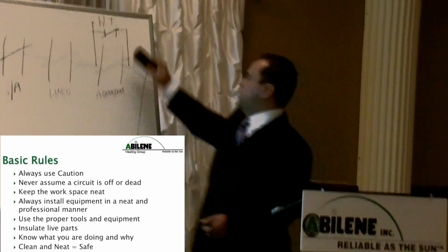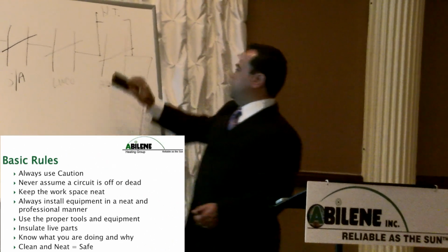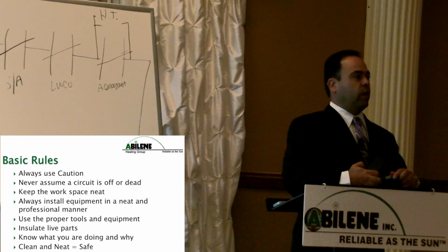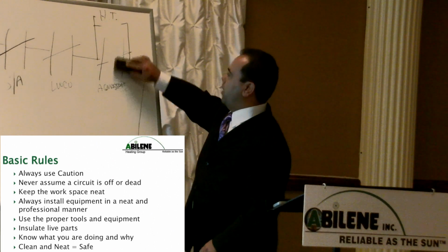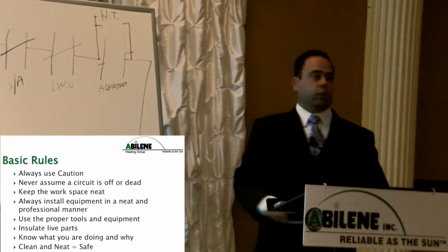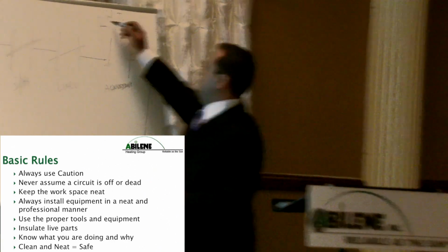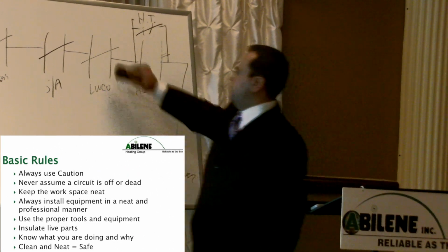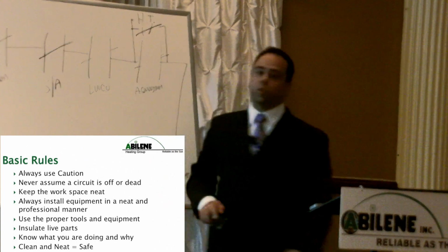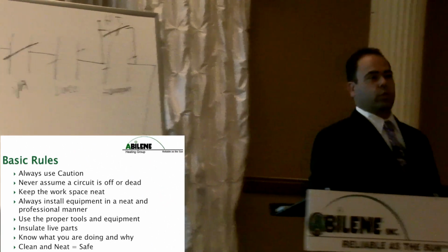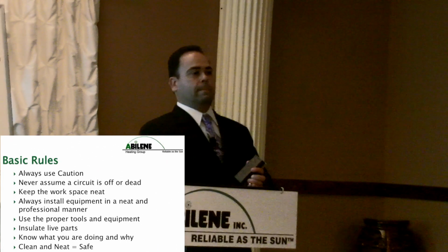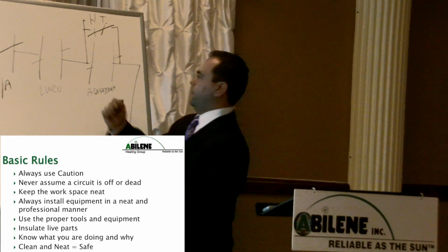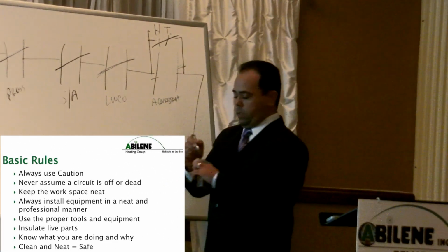If I open one, but I still need the other to satisfy, the burner's still going to fire, right? If I'm satisfied on both hot water and heat, the burner shuts off. I need heat. I don't need hot water. But all of a sudden, the boiler runs out of water. The boiler shuts off. Johnny? Can you see this from back there, Johnny?